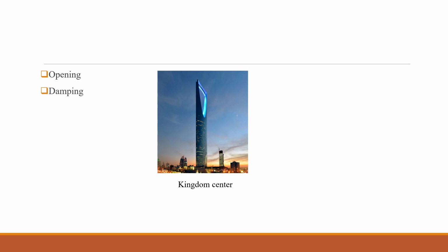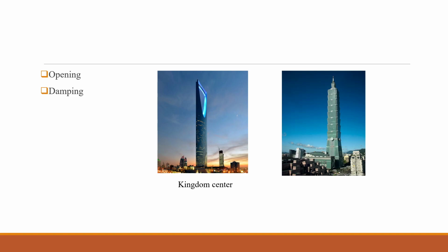Another method is called damping. Dampers are mechanisms designed to absorb energy from a building's movement, counteracting the effect of the wind. These incredibly heavy instruments are suspended, often on the upper levels of the skyscraper, and sway as the building moves, counteracting motion and creating a more stable environment for those inside. It has been used in the Taipei 101, called a tuned mass damper.